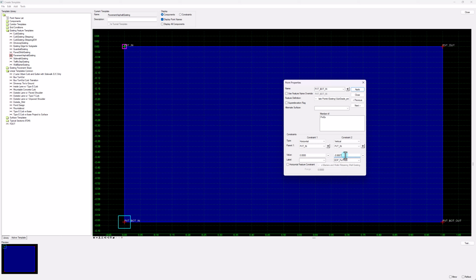But this will depend on when you go ahead and look at, you're probably going to get core asphalt or pavement corings that will tell you how thick the asphalt layer is, how thick the base layer is, and you combine those two together to figure out how thick your total pavement layer is, because it's your asphalt plus your base. And once you get into doing quantities and stuff like that, that entire thickness, the existing asphalt plus the existing base, is removed using the clearing and grubbing pay item. So it's important that we model all of that as existing, so that we're showing that as being removed under clearing and grubbing.